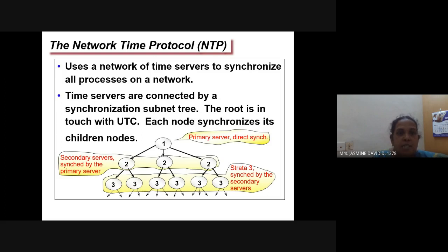Okay, so temperature. Because sensor nodes are deployed in various places, naturally the temperature variation will be there, right? The temperature variation throughout the day may cause the clock to speed up or slow down. For a typical personal computer, the clock drifts a few parts per million during the day. This is one research data. For low-end sensors, the drifting time may be even worse; this is for high-end. So next is noise.